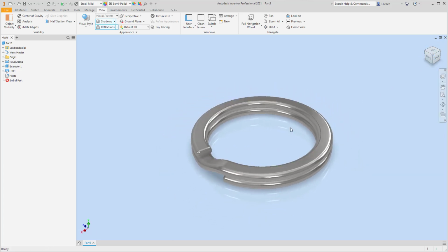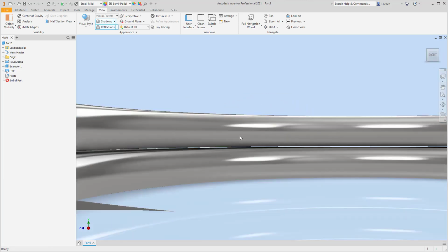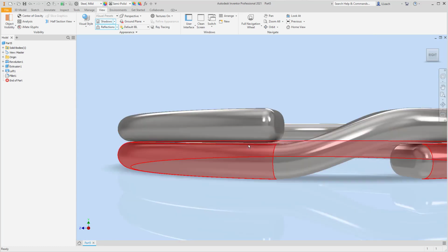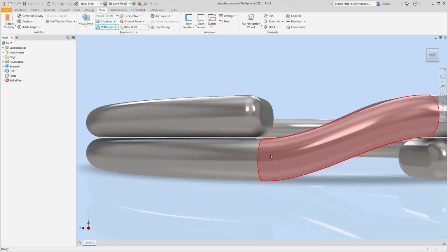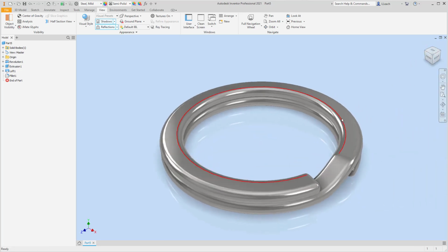All right. You can play around with the shape if you want to change it up, but that's how you do it. Just make sure that when you create your shapes, you don't put one right on top of the other. I tried it that way, but when you do that, you can't use the loft to connect these two. So that's the important thing.